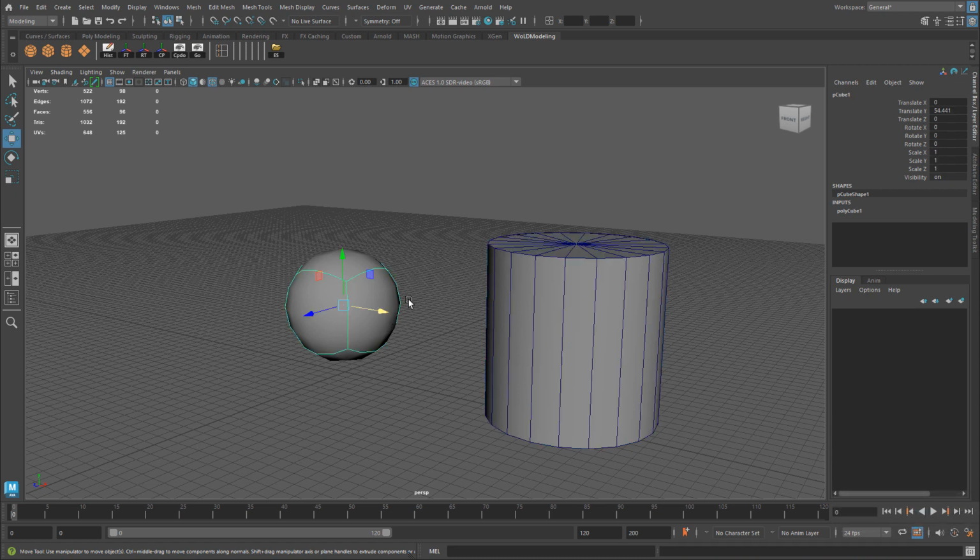the smooth mesh preview. So subdivision modeling mode is a modeling method that makes your meshes look really good, smoothed out when they are subdivided. And in Maya, you can preview how your mesh will look when it will be subdivided by pressing the 3 key. And for game modeling, you will not be smoothing your meshes out. You're not going to be using subdivision modeling method. So whenever you see your meshes collapse, that means you press 3. And to get them back into normal mode, press 1 to go back to polygonal mode.